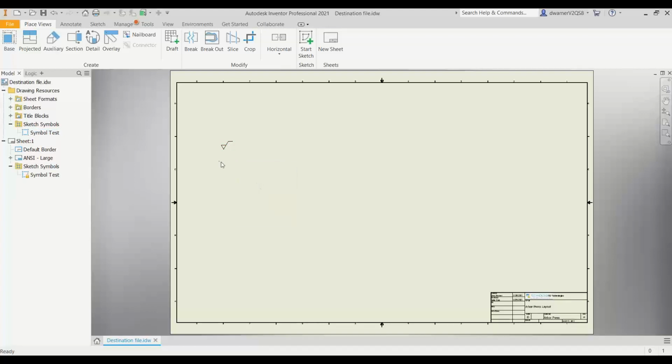So again, to go through that Drawing Transfer Resource Wizard, I did record initially saying no to overwriting the definitions. And if I were to go through that, you would eventually end up with copies underneath it. So you'd have a copy of ANSI and a copy large. And again, I'll run through that really briefly here.